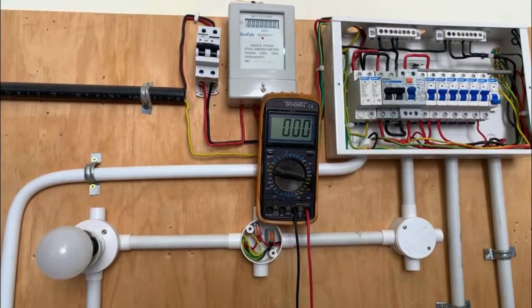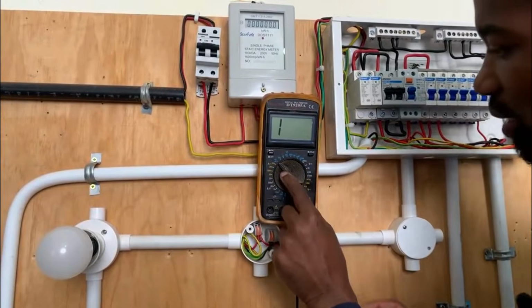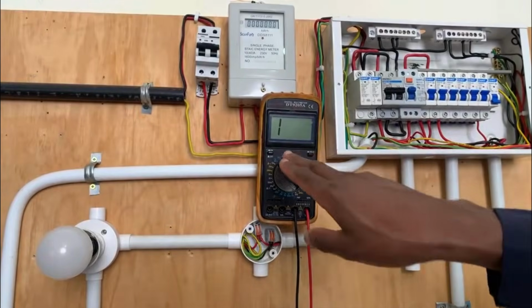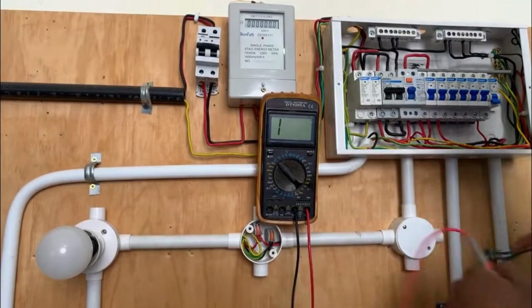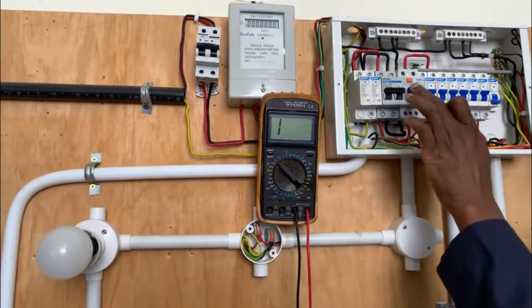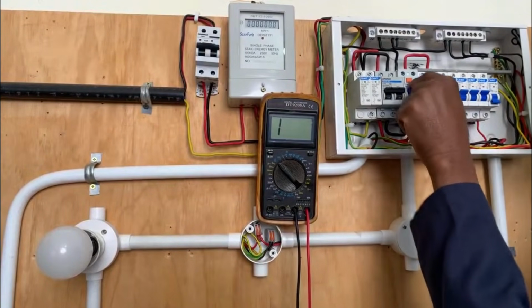Now, is there a point of taking readings between the neutral and the earth connection? One of the things that we need to record there is a continuity test. They should not be continuous, and I'm going to explain in a while. So we take the indicator or the pointer all the way to continuity, so that we can record between the neutral and the earth connection. There's no continuity. This is the reason why there should be no continuity between the neutral and the earth connection. Why? Because we have this important device here.